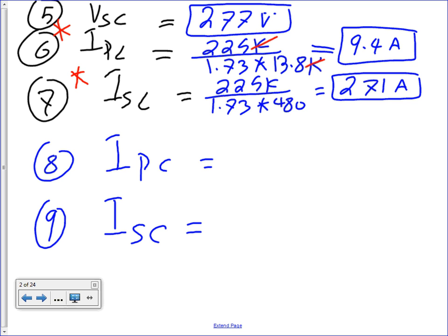Primary and secondary amps. The reason why I put a red star next to them is because this is what we size the feeders and the fuses based on: the line current and the line voltage, not the coil. The coil is FYI only.